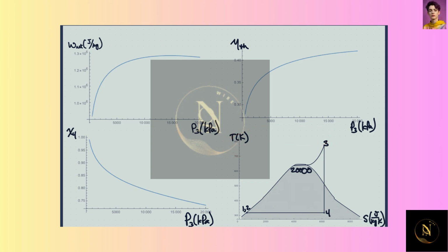I think there's not much else to say about that. The only interesting thing is that you can see max power does not occur when there's max efficiency. That's generally true in a lot of systems. Look at DC motors: where do you get the maximum efficiency of the motor, and where do you get the maximum power out of the motor? Not the same point. You might think they would be, because if it's more efficient it converts more, but that's not how things generally work. Efficiency and power out are different because the power in changes as you change things too.